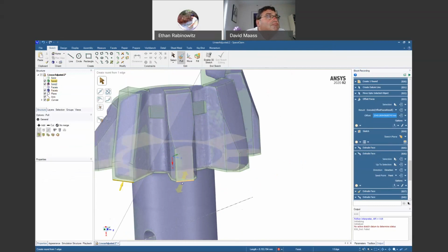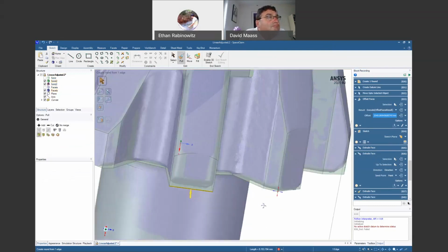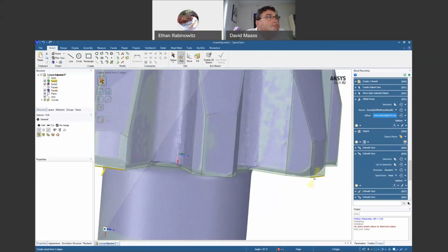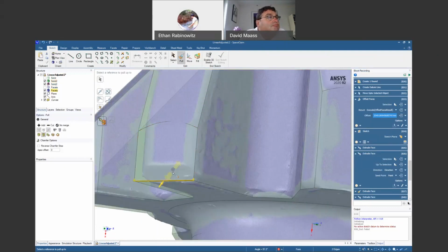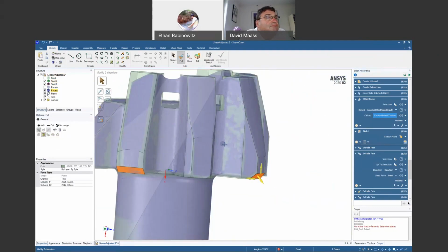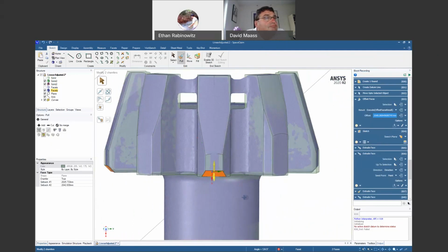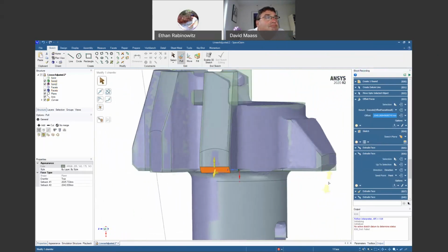If there's rounds and things, it looks like some of the edges have larger rounds, maybe chamfers. So these two look like they have a chamfer. Switch to the chamfer option, pull it up to, grab that in there. The other ones look like they may just be barely rounded, although that one looks like it's the same size. So I could pull that up to this other chamfer. So they're the same size. Oops, here's one more. Up to this one.